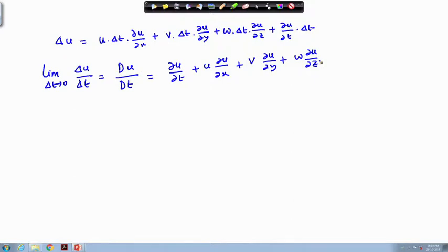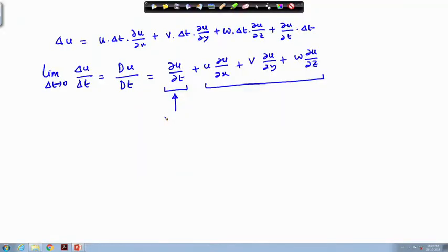I just went on doing the entire derivation because from my personal experience I know this is a concept students have very great difficulty with. Once you explain this properly, you can clearly highlight that fluid acceleration is different from rigid body acceleration, in the sense that in rigid body acceleration you always have a temporal term, and that is the only term. In contrast, in fluid acceleration you have both a temporal and a spatial acceleration. This is very important to explain to the students, and once they understand it, you can rely on this to make significant further progress, including in the conservation equations.